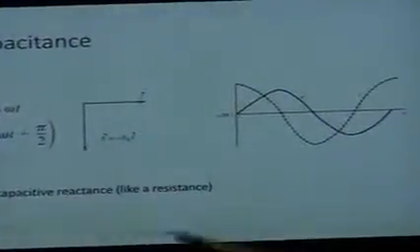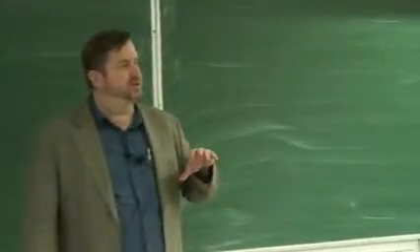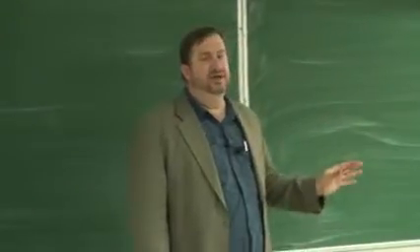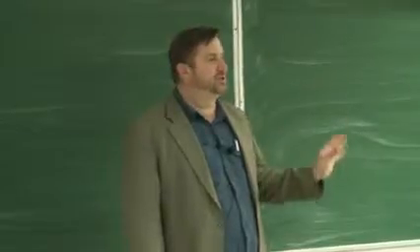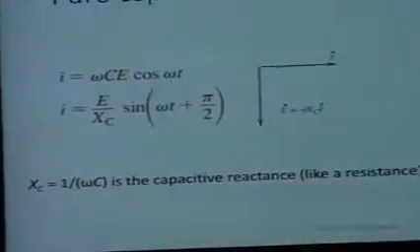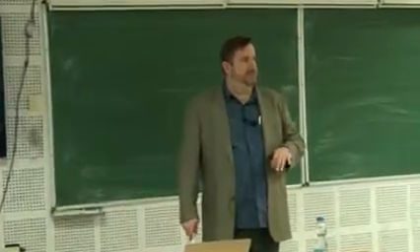But this capacitive reactance is something that's important. It is frequency dependent. And that's going to become important as we look at analyzing these materials, because I could actually tune that out. I can tune that out in a real circuit by essentially making this X sub C become negligible by going to very high frequencies. Because when I go to very high frequencies, that reactance will go to 0. And we'll see how that affects things in some of the impedance spectra that we look at.